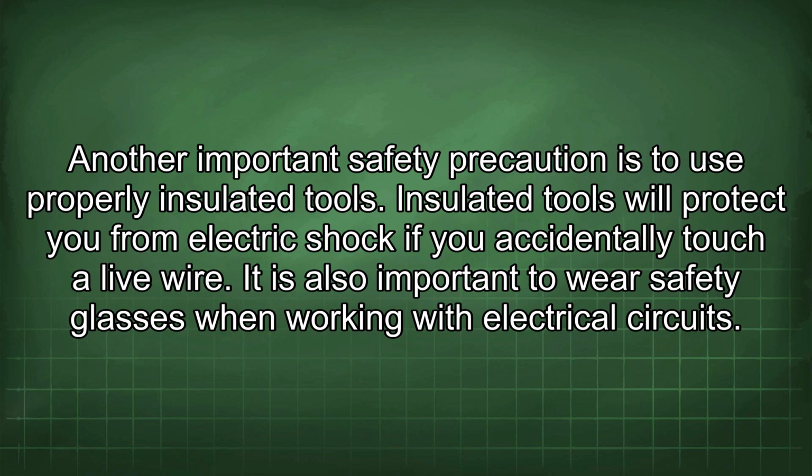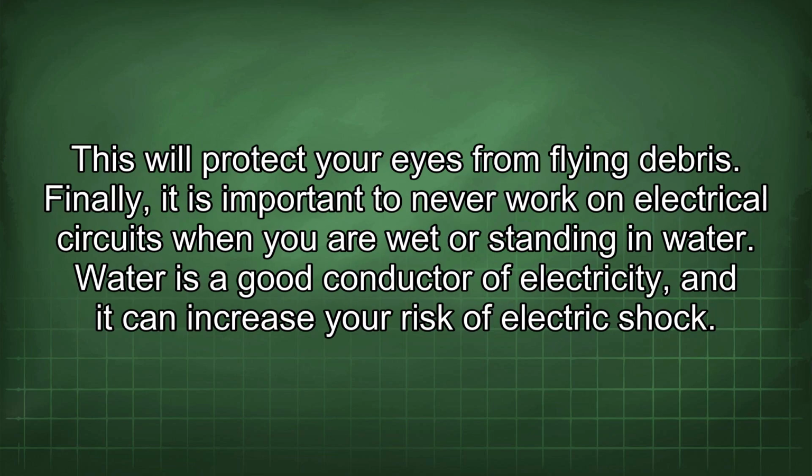Another important safety precaution is to use properly insulated tools. Insulated tools will protect you from electric shock if you accidentally touch a live wire. It is also important to wear safety glasses when working with electrical circuits. This will protect your eyes from flying debris.